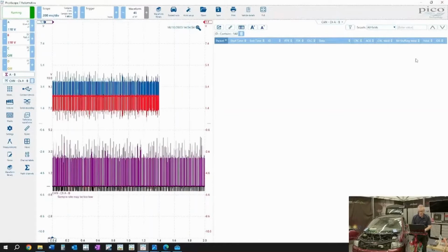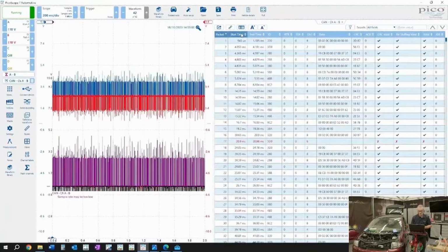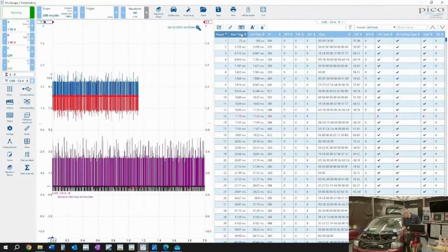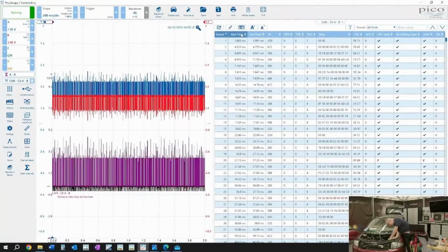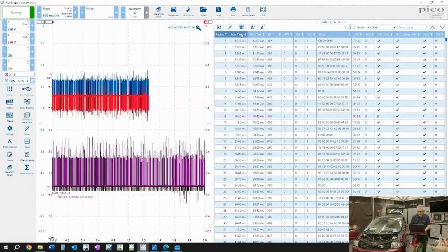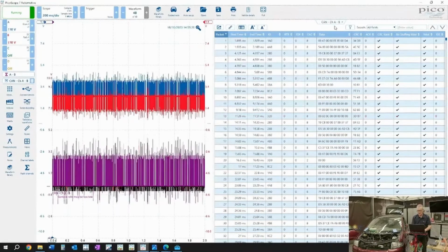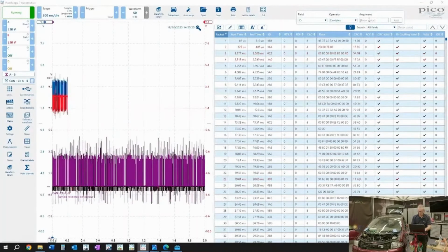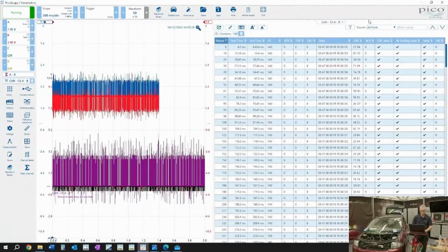If I erase the filter, now we're getting all the CAN traffic as we had before, but 1A0 is not present. Okay. Now if I reconnect, if disconnection was difficult, oh, there we are. We should see 1A0 appear again. I can see it there. And then just to confirm, if we go back to the filter, contains 1A0, yeah, it's back again. All right.